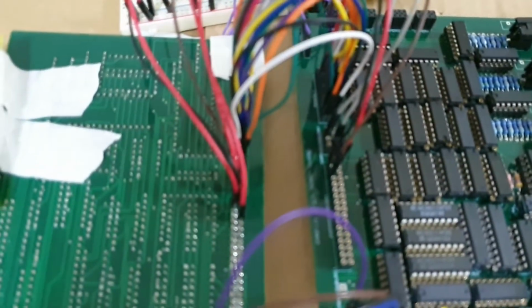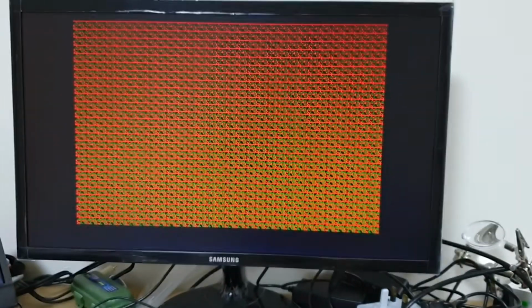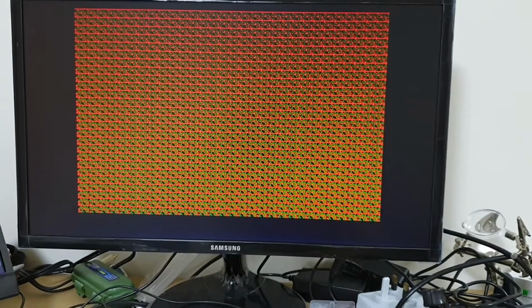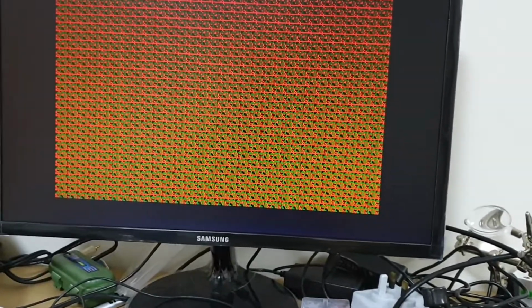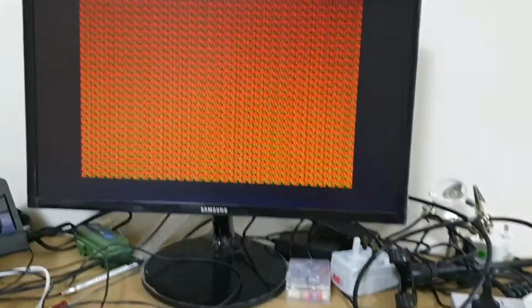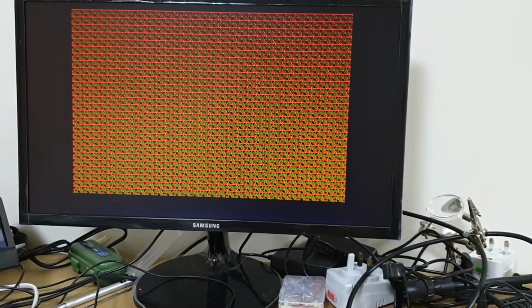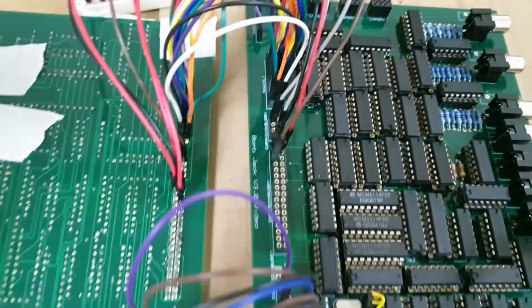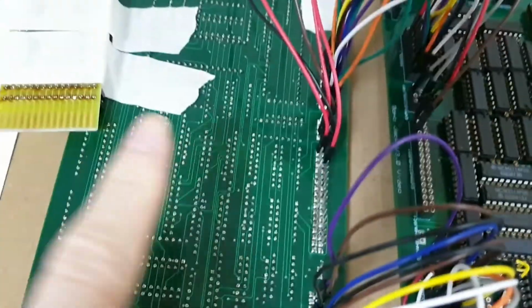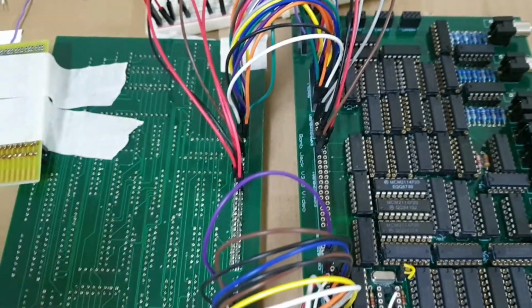I've just conducted a quick character bitplane RAM writing test to check, and the result is that one row of the same character is all the same bit. It's that kind of reddy browny color, which is good, because previously when it powered on, it was a bit pattern. So that's okay. That actually means that the test for addressing the RAM on the character generation board is working properly now, and it's writing in a stable and expected manner.